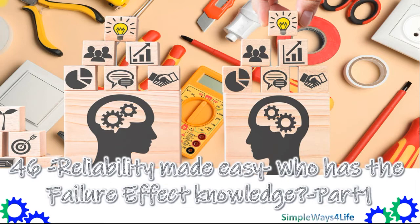When you invite the manufacturer, they don't come, but the designers come with some expert teams. Either they are making the commissioning in the field, or some experts from other plants who use these equipments, and they send them to you in the reliability centered maintenance analysis team. And these people are able to tell you the failures that might happen to your equipment. If the manufacturer has already prepared this documentation, or is ready for this analysis, he can sell it to you, and you can take it and put it inside your reliability centered maintenance analysis, so you can make proper selection of maintenance tasks, and you know the consequences of each task and what might happen in case of each failure that happens.